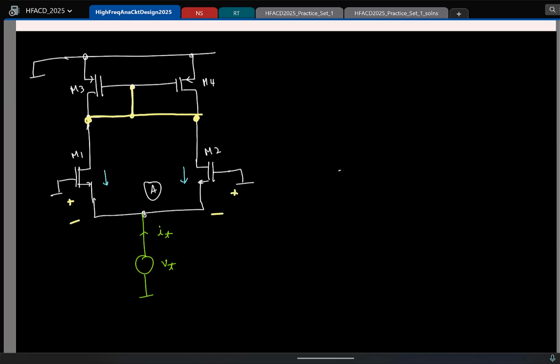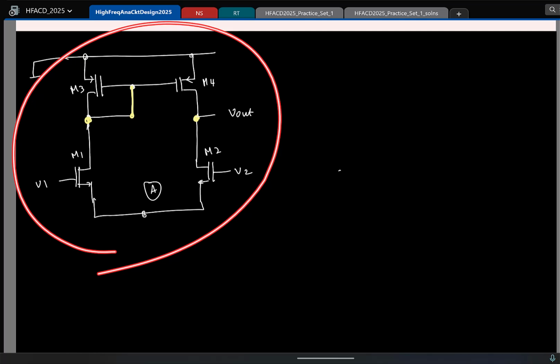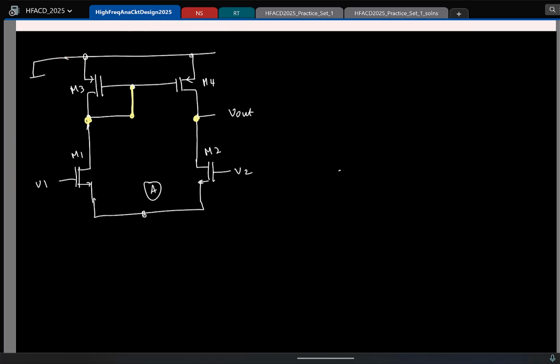So now at least we know that if I have common mode inputs, I can say that the circuit is symmetric, right? So now, earlier how did we find the small signal gain of the circuit? I mean, how did we actually compute the small signal gain? Yeah, but V0 by V1 minus V2 is the gain, but what is the approach we took? How did we find it? Short circuit GM and the output resistance.